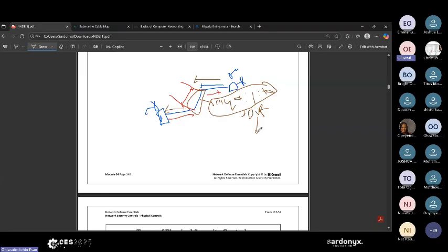In foreign countries, you can see that security cuts across almost everything. Like on some systems, there can be a loop, and you'll be seeing the same thing. And that one is even crazier. And there's something about these CCTV cameras too: if you don't install them well, you have the signal cable and also the power cable, and the power cable can actually affect the signal cable.